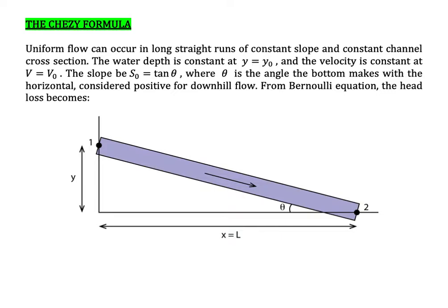Today I would like to share with you a few equations that are commonly used in open channel calculation. Previously, we discussed the Reynolds number and also the Froude number. In open channel, we use the Reynolds number to determine whether the flow is laminar or turbulent, but you must make sure that you really understand how to calculate it, because we are not using diameter or length.